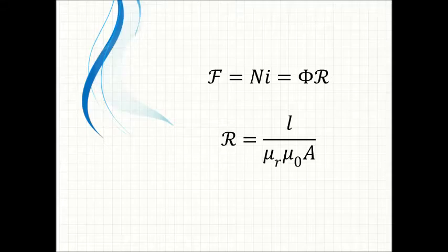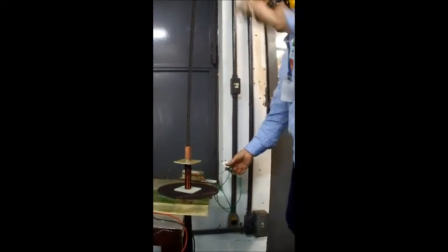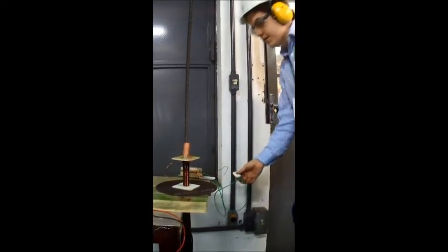Once the length of the rod was so high, the reluctance was so high, and the current needed to generate the magnetomotive force was so high that it burns the copper, burns the varnish, and begins to generate some smoke. And we stopped the experiment earlier rather than later.